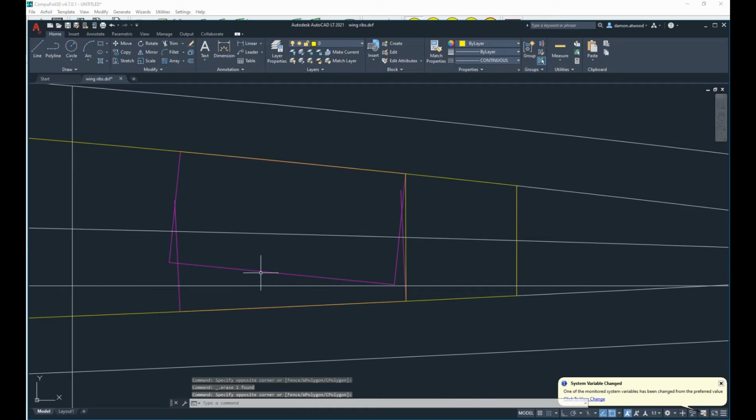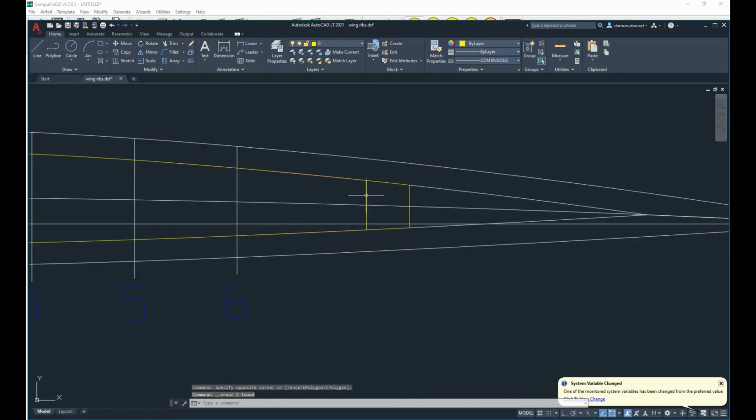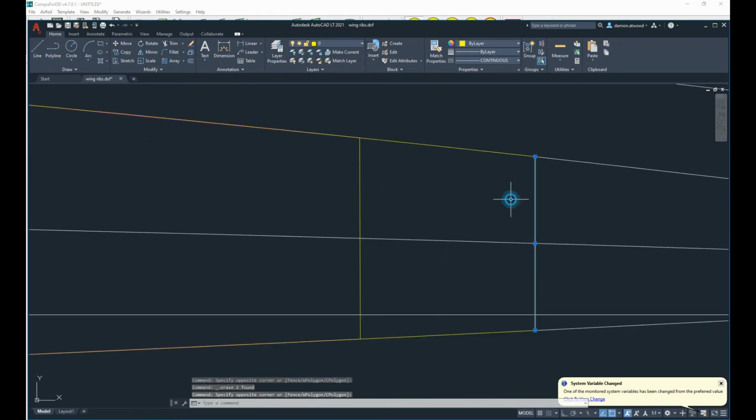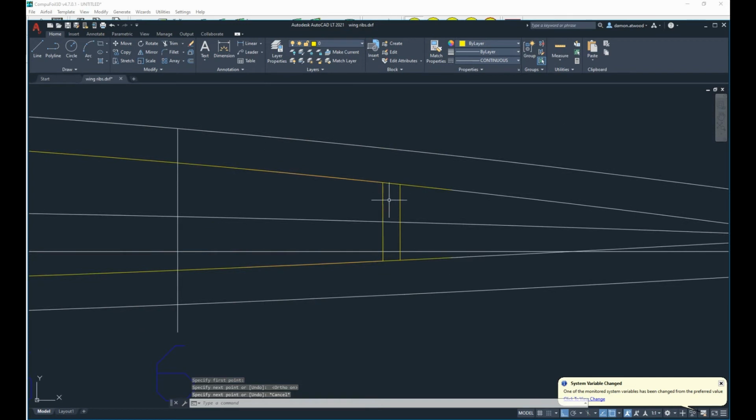Because the way him and I build wings, he is essentially going to have about an 1/8 inch piece of material right here as his trailing edge. He'll glue on a 1/8 inch trail. Actually, his 1/8 inch will go all the way to the skin, is the way he does it.